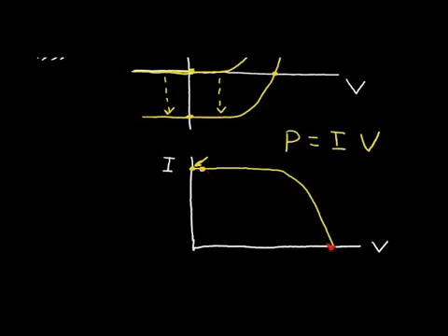Now let's look at this point over here. At this point, we have no current flowing in the solar cell. So the circuit is open, and we're looking at a high voltage. But since our current is 0, we extract no power, so that's not very useful. But if we can operate over at this point, then the power that we can extract from this cell is the area under this part of the curve. It is this amount of current times this amount of voltage here.